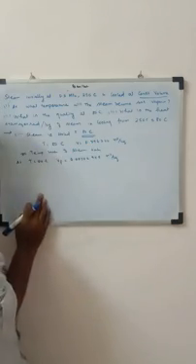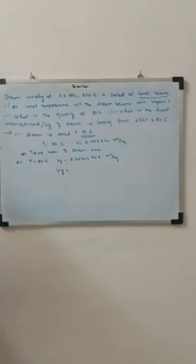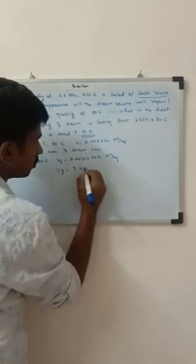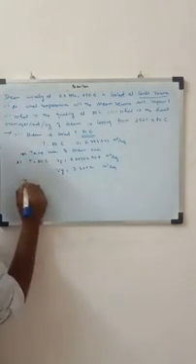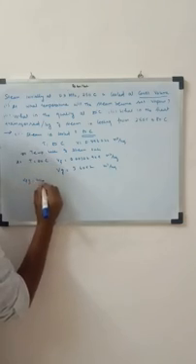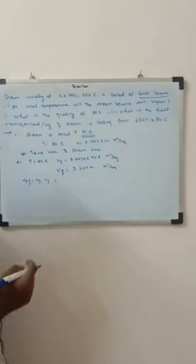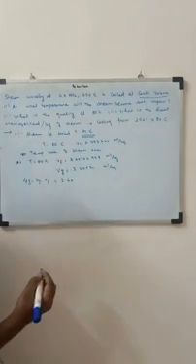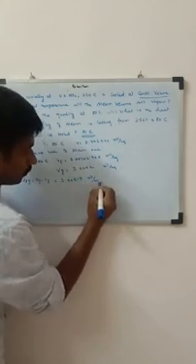And then I'm going to write down my Vg. Vg value at 80 degrees is equal to 3.4052 meters cubed per kg. And we know that Vfg is equal to Vg minus Vf, which gives 3.40417 meters cubed per kg.